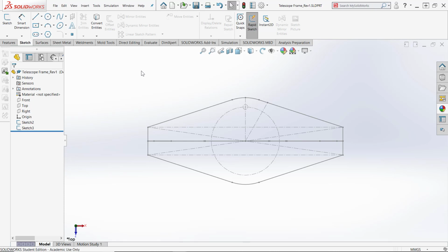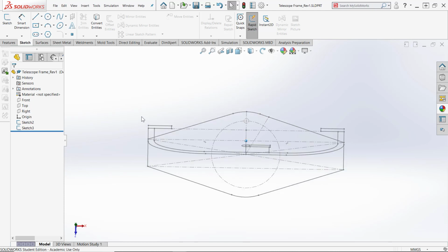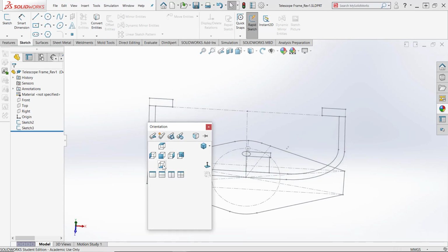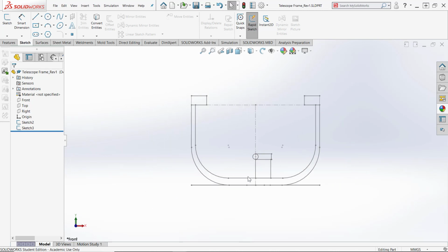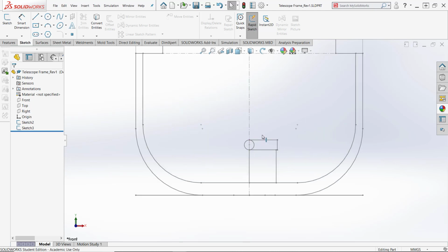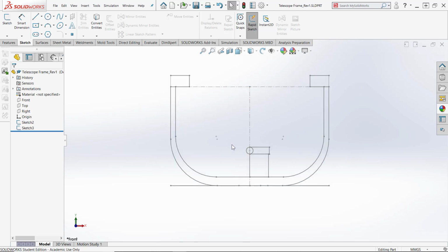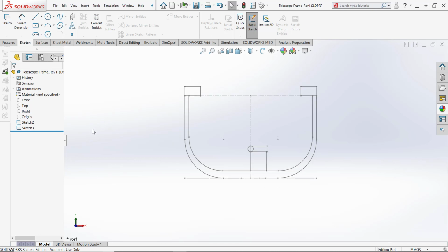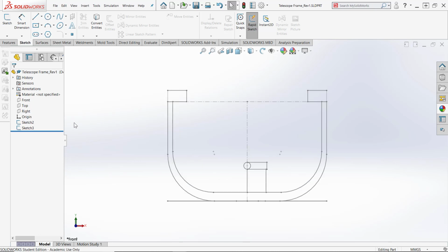and then I'm going to go back to the front view, and later on we'll put a hole in here, a counterbore hole. And because the counterbore hole goes from the bottom up, I have to do a little bit of calculations, and I try to avoid doing any calculations if I can. So I think I'll do the sketch myself rather than use the hole command. There may be reasons though where you want to use the hole command for putting fasteners in your part.